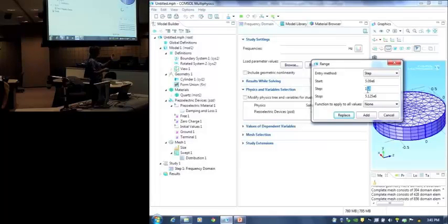So you get the resonance frequency, then you want to sweep around that resonance frequency, but you have to be very careful about the step size you choose for stepping the eigenfrequency. You don't want to step too big. If you step too big, you'll completely miss the resonance spot, and you'll just see a response that linearly increases with frequencies. You won't see a regular frequency response curve. So the frequency stepping should be small enough.